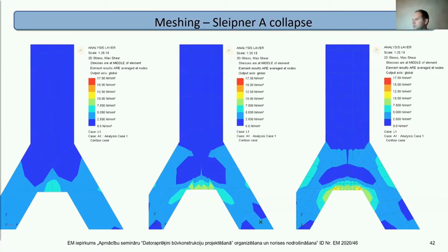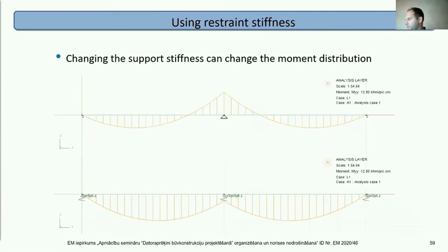Okay, there is I guess at the moment some 3 questions left, and one question is regarding slide 59. Yes. So the bending moment is the same as for a simply supported beam and no hogging moment because of the spring stiffness. Did it have any effect on lateral torsional buckling in this case? It might do. I mean, this was just a static analysis.